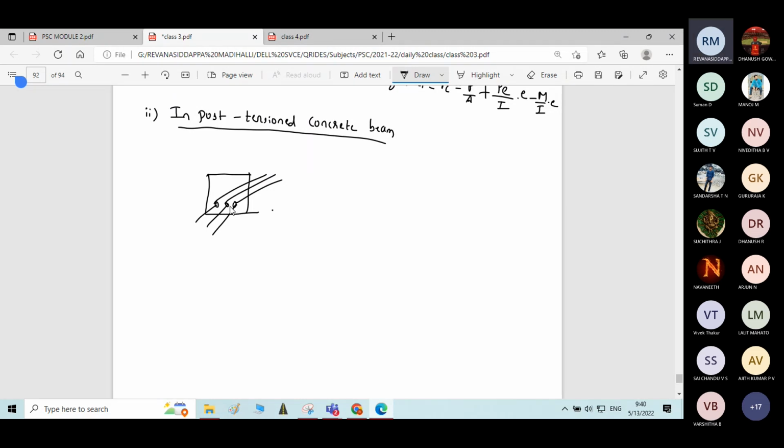Understand? Here, in case of post-tensioning, the tensioning of the wire will be done after the placing of the concrete and its hardening. So if these wires are stretched simultaneously and released, whatever stress is induced in the member, the initial pre-stress P is recorded after the loss due to elastic shortening only. Already it is considered at the beginning stage only.